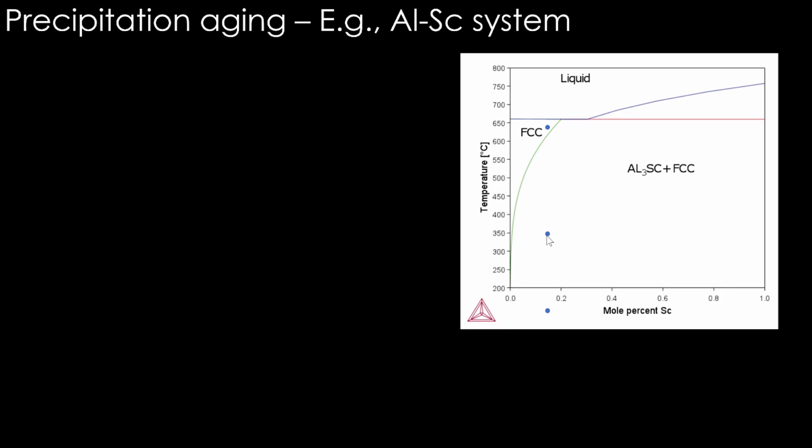When that small amount of diffusion is permitted, immediately nucleation starts everywhere uniformly, not only at the grain boundaries. Then we heat treat it at that temperature for a certain time. All this homogeneous nucleation happens, precipitates grow uniformly distributed everywhere, so that the hardness or strength, if you check, will be maximum after a certain time. Okay.